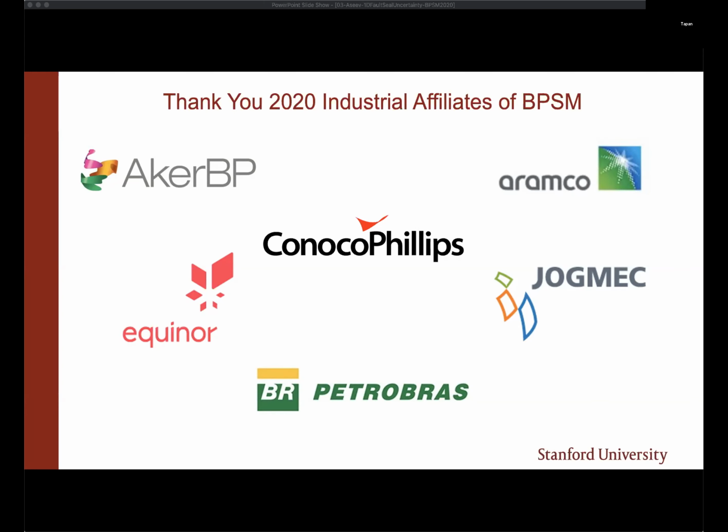Are we violating the range of validity of that equation? If it's a physics-based equation, maybe it has some simplified physics. Maybe it's linear elasticity. Maybe it is ignoring anisotropy. So depending on the context, it could be that we are violating the range of validity of that equation, or it could be that it doesn't incorporate all the physics or all the conditions, and so that's why it is giving unrealistic results. So it could be both. It could be the equation is wrong, or it could be that we are applying it wrongly.